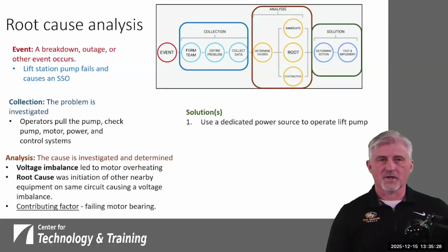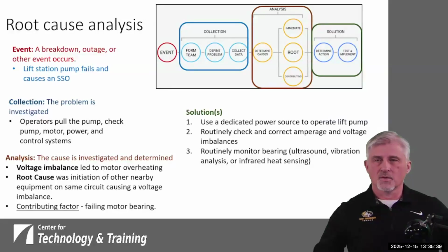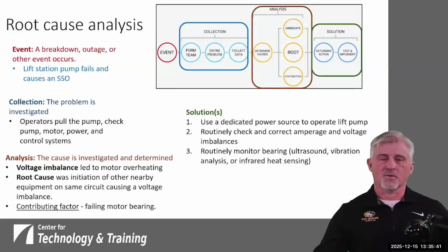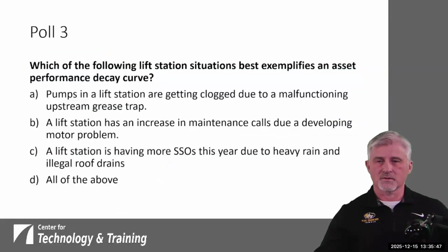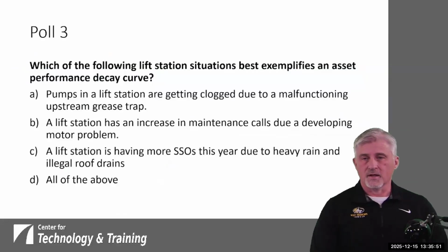All right. So to solve this, we're going to use a dedicated power source to operate the lift pump. We're going to routinely check and correct amperage and voltage imbalances. We're going to monitor the bearing, whether using ultrasound vibration analysis or infrared heat sensing, or a combination of those. And then we're on to our poll 3.